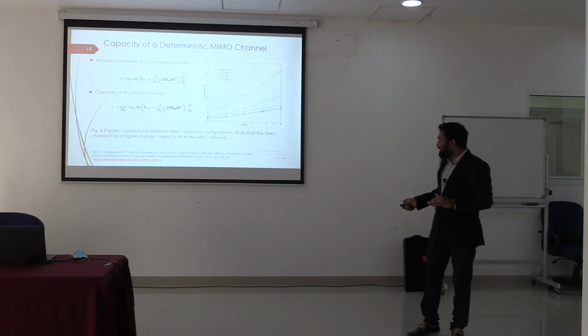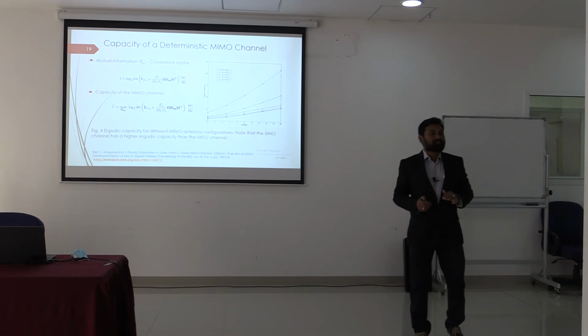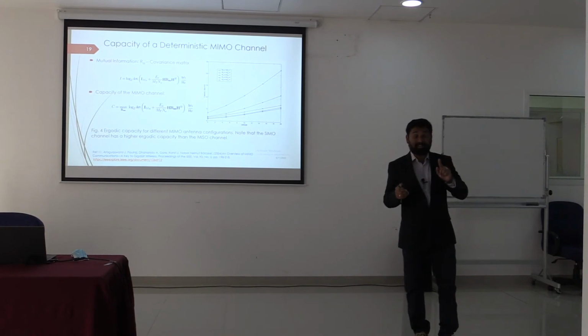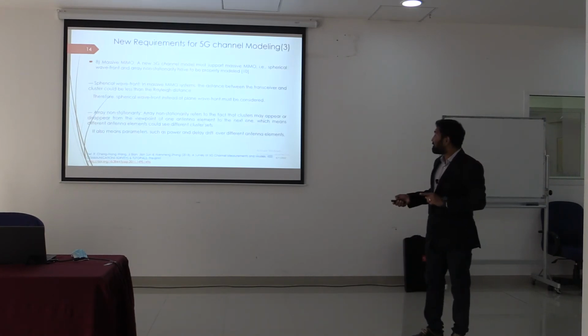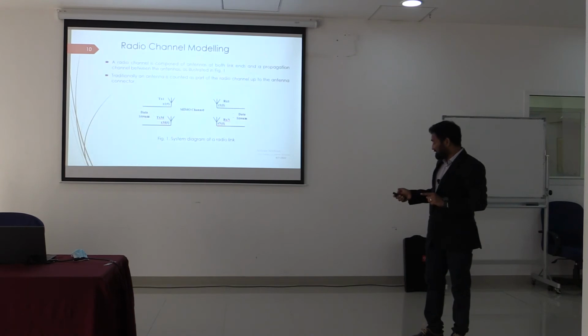They calculated this gigabit wireless data rate using MIMO, but they assumed theoretically the channels are deterministic, so they can transmit maximum information based on the autocorrelation function. So they are estimating the autocorrelation function between the, yes, they are transmitting the same information from many transmitting antennas, and then receiving by many receiving antennas.